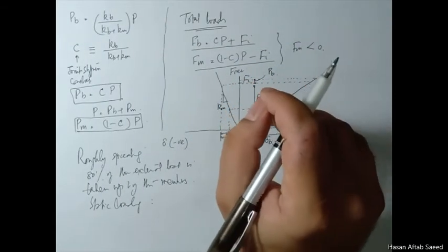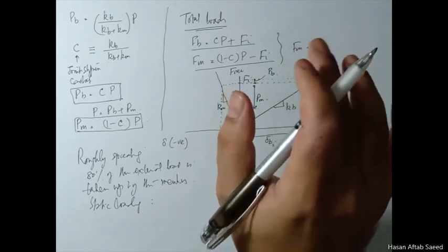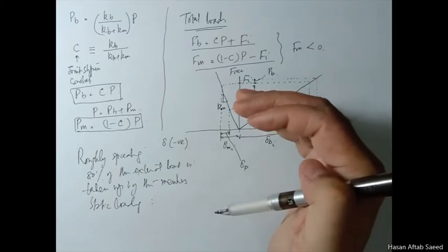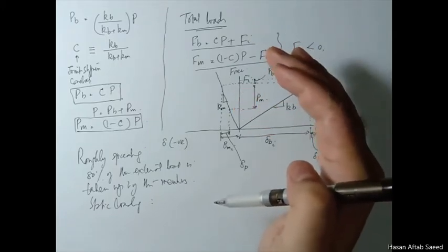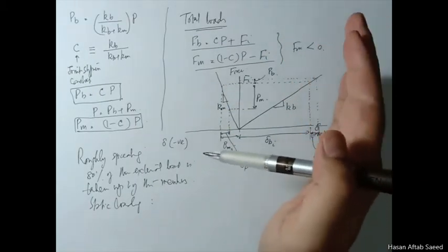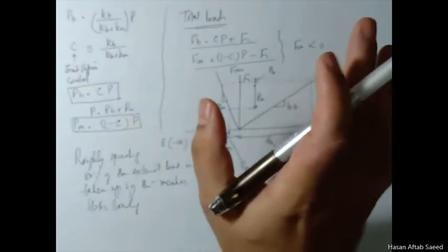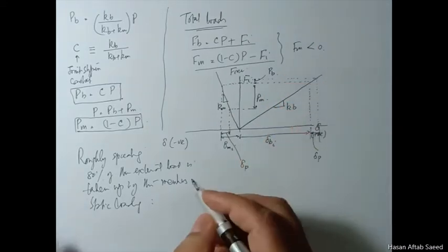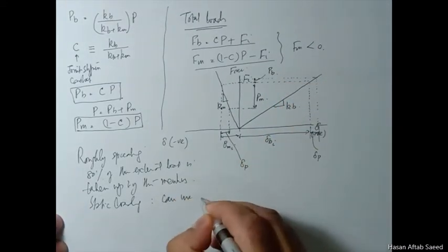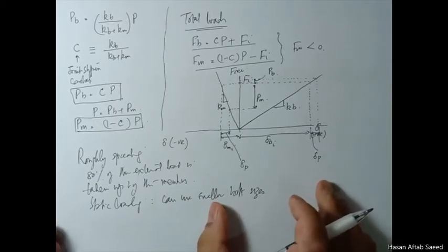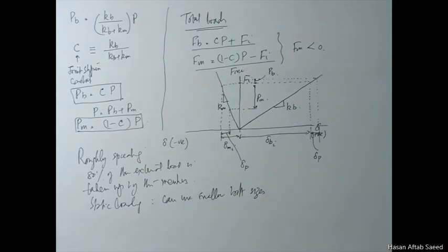Because you know that even if I go very close to the strength of the material, there's nothing to worry about, because when I apply the load P, most of it is going towards the members anyway. It's not going to increase the tension in the bolt, so I need not worry about that. So I can go to a very high percentage of the strength of the bolt. So you can use a smaller bolt size. By smaller bolt size, I mean we can use bolts of small diameter. Now what about fatigue loading?